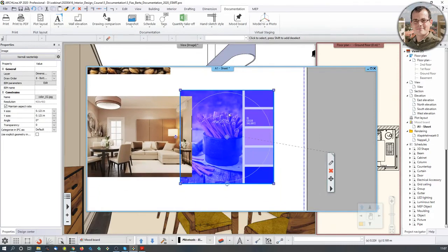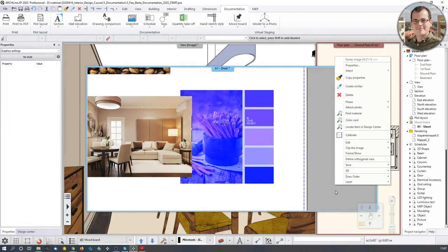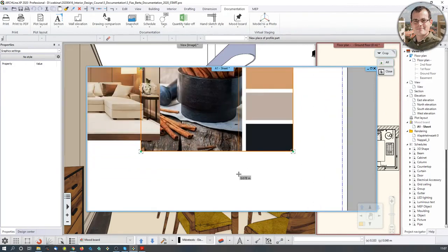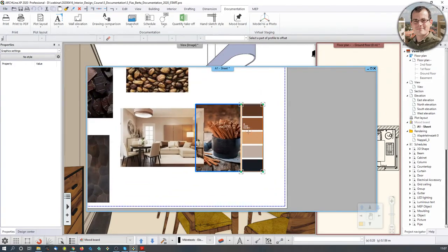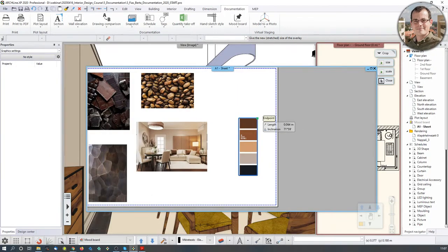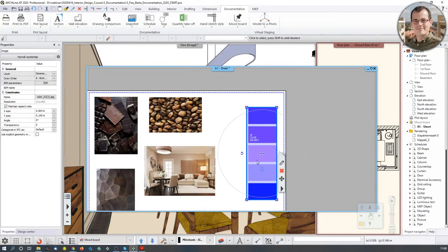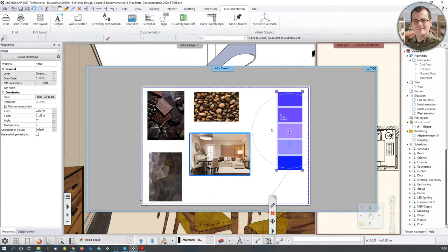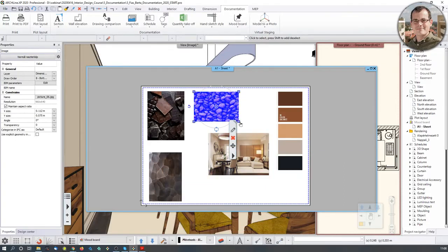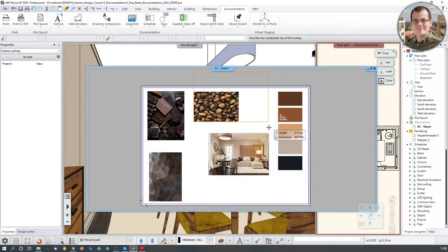So what do I do? I go to the local context menu of the image while it's selected, go to this arrow over here, and I'm just going to say clip the image, and we're just going to crop the image back. So now the image has these kinds of guidelines, and if I click on the sides, I can trim the image back. So that way I only see, once I hit enter, what I want to see. So again, I think now I could even scale it back up. So I'm just going to do it just like that. So one image should be here, and another image should be there, and this image should be made a bit larger. Yeah.